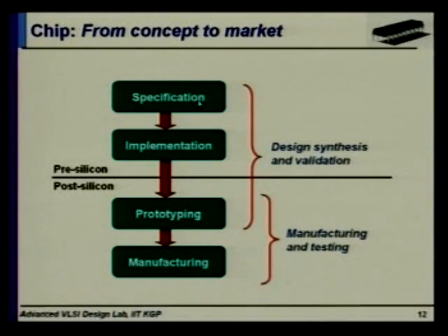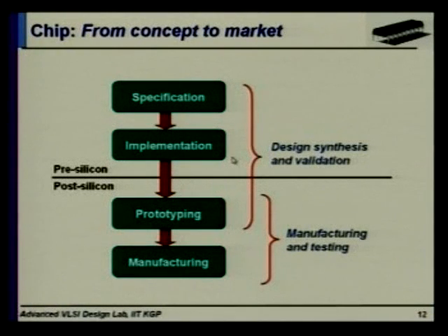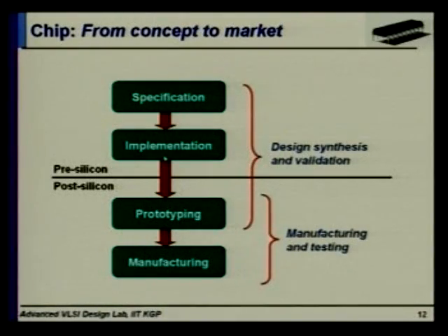In the pre-silicon, we typically start with the specification of the design and then develop the design. Here we use different kinds of languages. For analog design, you can use the schematic editor, and you can use languages like SPICE or Verilog-AMS to describe models of circuits. In digital design, you will use Verilog or VHDL to describe the implementation, and then there will be synthesis tools which will take it down to the gate level design, and then the transistor level design, and then to the tape out.